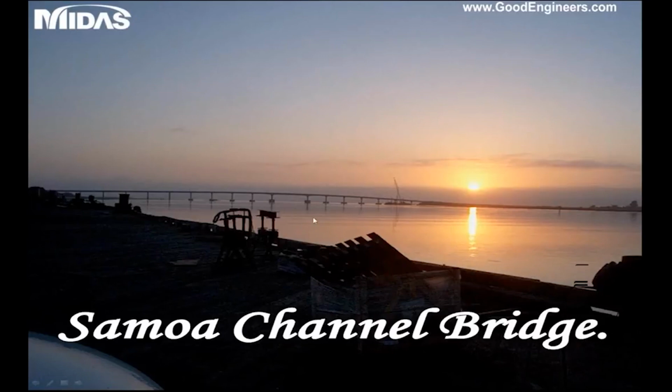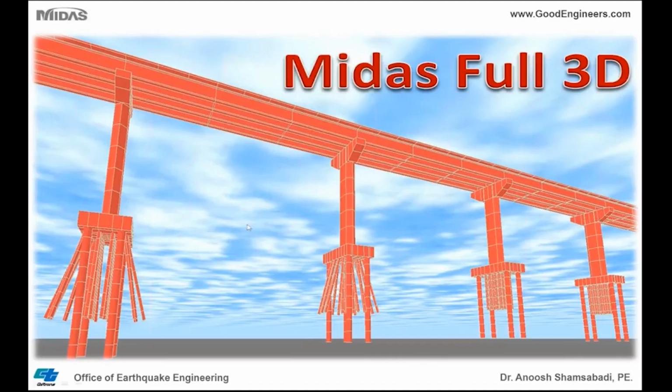So this is the schematic view of the bridge. This is a rendering that I've done with Midas, full 3D option in Midas. You can see the superstructure is composed of a composite deck, including the prestressed post-tensioned beams, 4 beams, supported on hexagonal columns. Like I said, massive pile caps, including this photo, which is from the rendering of the Midas, shows the pile caps, including existing piles and retrofitted piles.